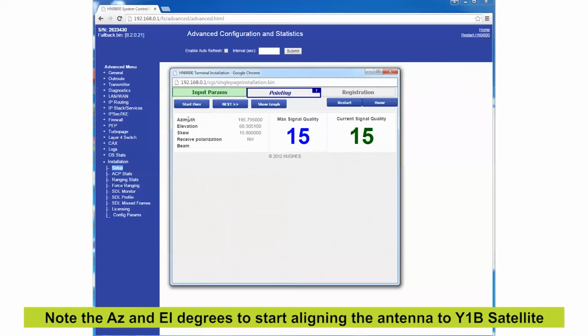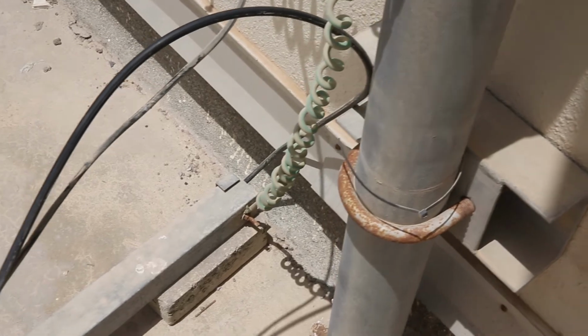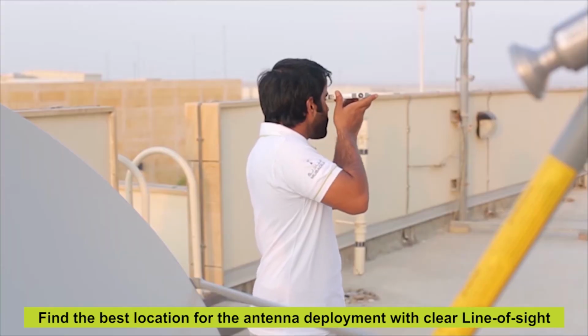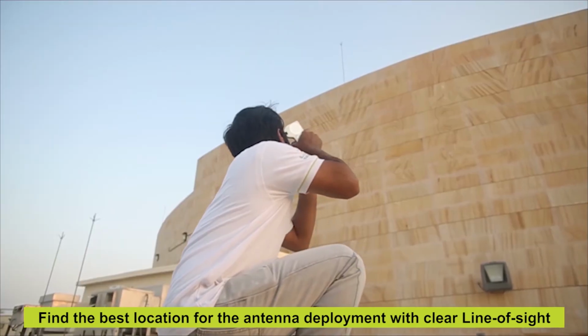The same azimuth and elevation should be used to start pointing towards Y1B satellite. The signal power is shown as 15 at the starting point. The installer should consult the customer while searching for a suitable location to place the antenna.